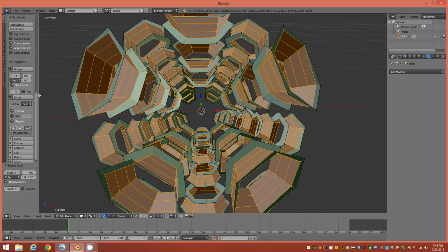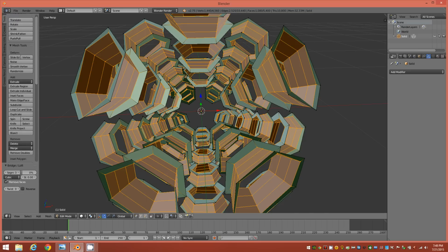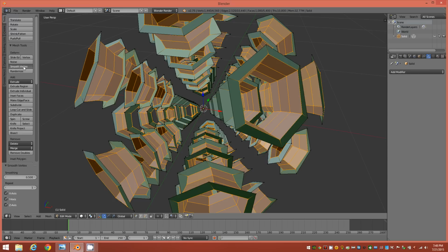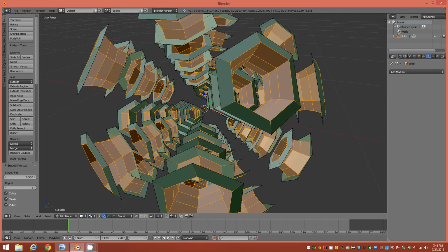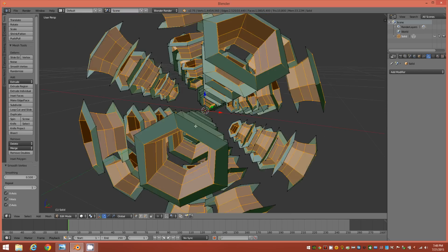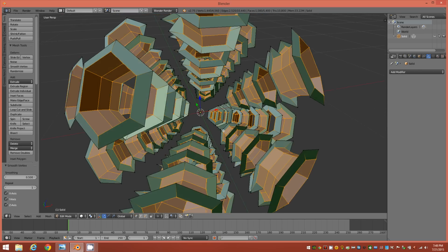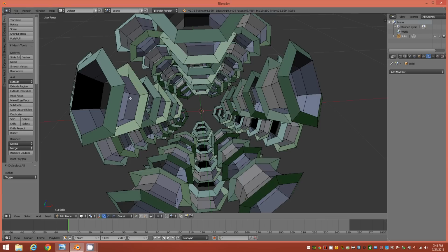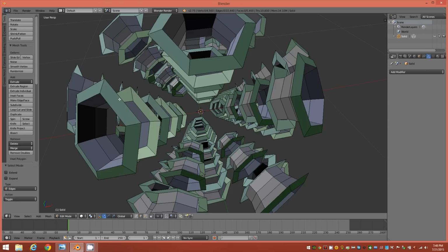The next step, with everything still selected, the new bridging selected, we'll just tap on Smooth Vertex twice. That'll smooth it out and give it a little bit better edge flow. Now that we have all that, we'll go ahead and bridge the outside edges. So you can deselect everything and switch to your edge tool again.